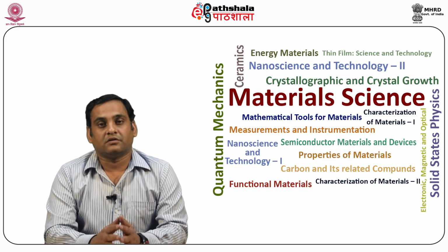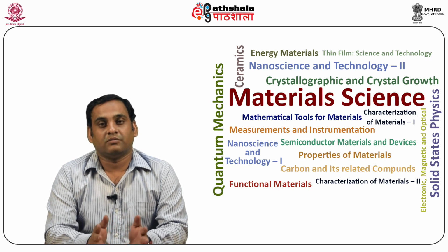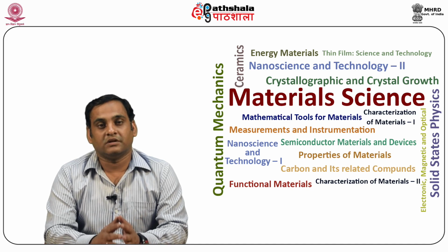Rotation of the Ms vector of a domain always produces a dimensional change, because the spontaneous magnetostriction depends on the direction of the Ms vector relative to the crystal axis. Thus, in the general case of a crystal being magnetized in a non-edge direction, the magnetization process will involve 180° and 90° wall motion and domain rotation. The last two of these three processes will be accompanied by magnetostriction.